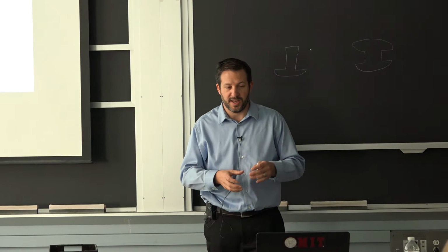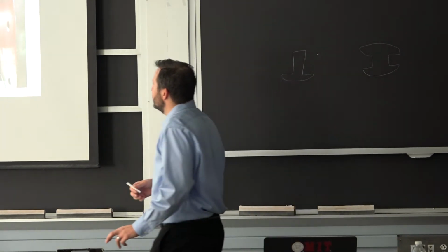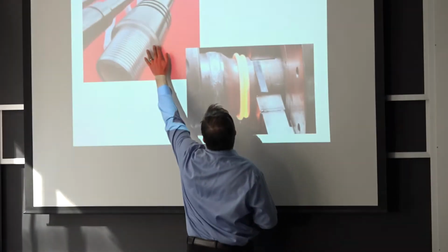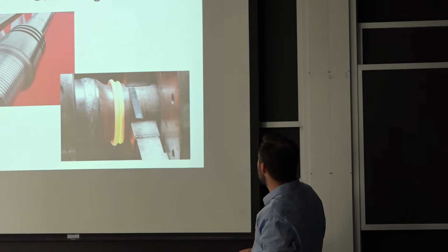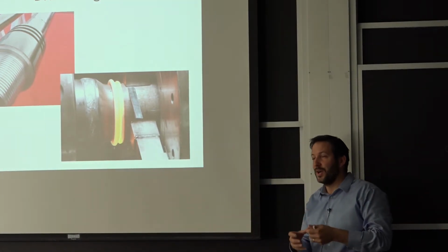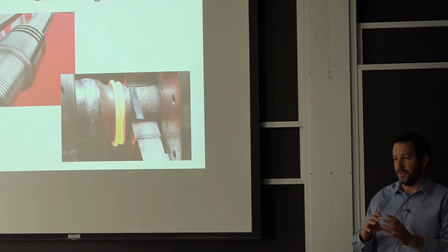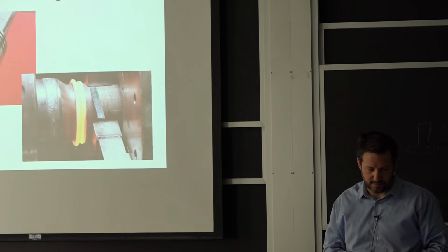You don't have to have this change in section, because when the joint is included here, you see that it's much bigger over the joint than it is on the base material. There's another thing to note: this region of the weld has a bigger cross-section than the plain pipe itself. So that's a practical way they make sure that they don't have the highest stresses.